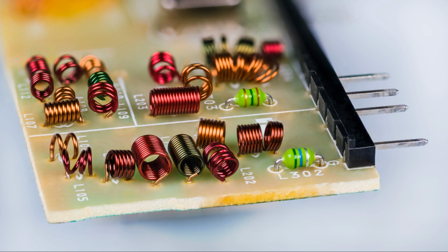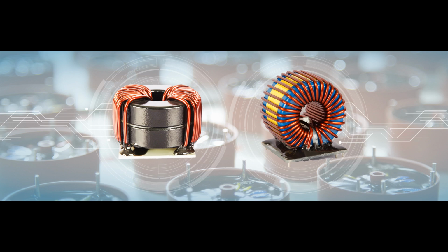In mechanical systems, particularly internal combustion engines, a choke is a mechanism used to control the air-fuel mixture during the engine's startup phase, especially when it is cold. The choke is a part of the carburetor system, and its primary purpose is to restrict the amount of air entering the carburetor, allowing more fuel to enter the engine. This enriched fuel mixture makes it easier for the engine to start and run smoothly when cold.